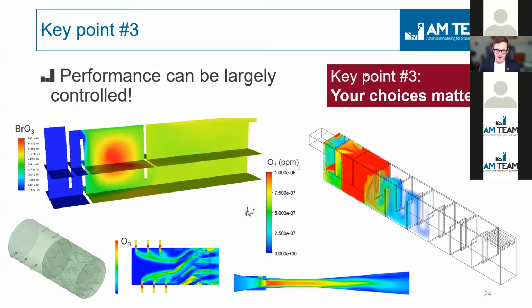And yes, full-scale reactors have non-ideal dynamics. So mixing is very complex. You always have some short-circuiting, some dead zones. For example, in this reactor, you can see some rotating zone. I agree, it's a poorly designed reactor, this one, but we are showing a quite extreme case in this case.